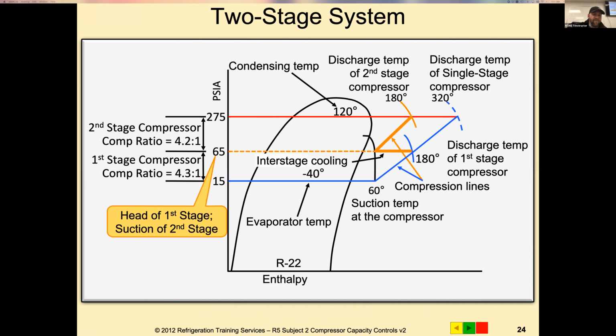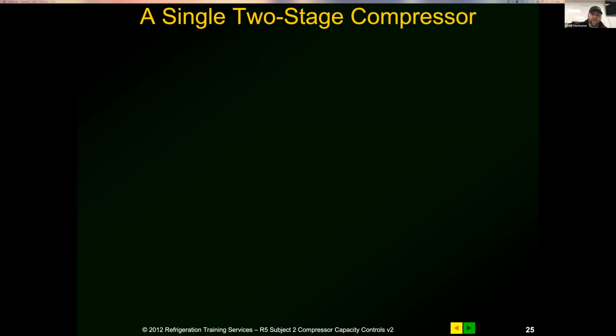So every manufacturer, if you guys have ever been to a manufacturer's seminar on their compressors, the first thing they're going to tell you is cool gas keeps compressors alive. So that's what this is all about. Cool vapor getting into those and having enough vapor there to absorb the heat necessary to keep the compressor cooled down.